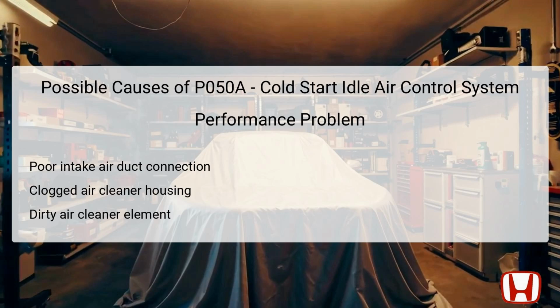Another potential cause is a clogged air cleaner housing. If debris obstructs airflow, it can severely impact engine performance by preventing the air-fuel mixture from achieving the desired ratios. Additionally, if the air cleaner element is dirty, it can further limit airflow, exacerbating idle stability issues. Each of these components plays a vital role in engine management, so addressing these causes is fundamental in resolving the